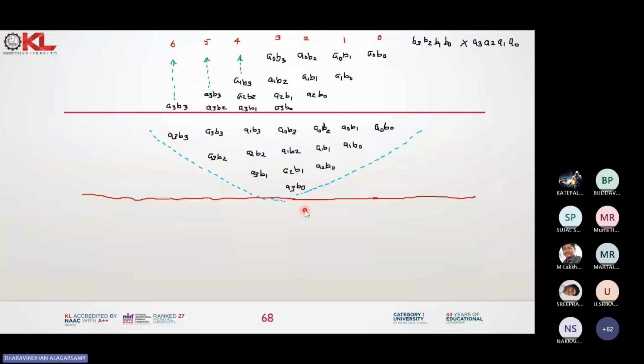In this Wallace tree multiplier, after reforming your partial product like this, now we will select the initial structure of your partial product from the top of the tree. That means from the center of the tree. First, I will select this at the top of the tree, and after that, I will select the left hand side of the tree. I will combine these two together as one, and after that, on the left hand side, I will combine these two together as one. So I'll write this as the first block, and this as the second block. Any doubt on this?